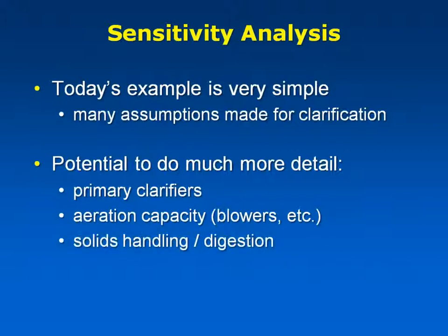Solids handling, digestion: is your system going to run out of solids handling capacity before it runs out of treatment capacity? Influent concentration changes. If you were in a position where maybe the hydraulic loading, maybe not the flow, is your problem, but a sudden change in influent concentration, either up or down, is a particular problem for you, you can do these types of sensitivity analysis and scenario analysis along with CapdetWorks to put a dollar sign on it, and that can give you a lot of interesting information.